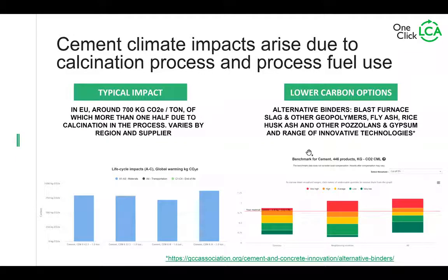And there's a lot of variance for cement, but the very lowest, GCPS, is the same as blast furnace slag. What I was going to say is that in the lower end, you can see there's a great deal of variation in the carbon footprints of cements, but these are predominantly achieved by using alternative binders, and the alternative binders do usually have a bit longer curing time.